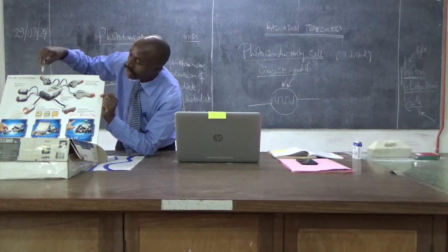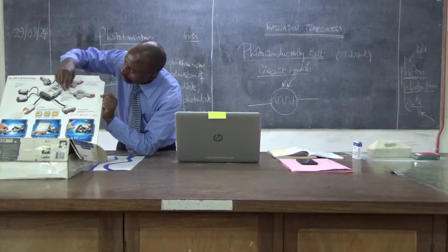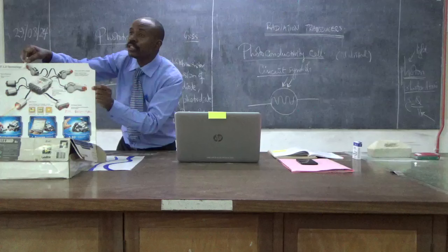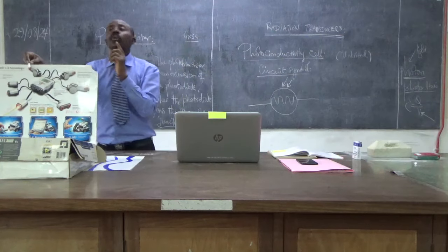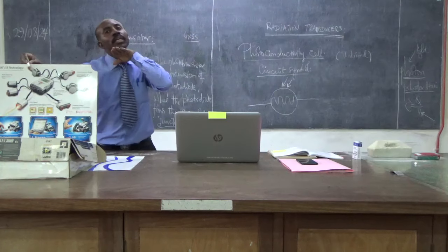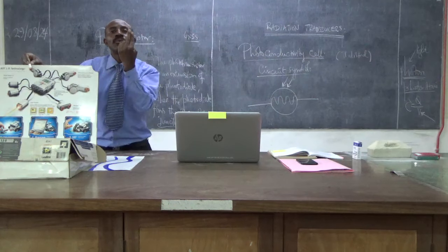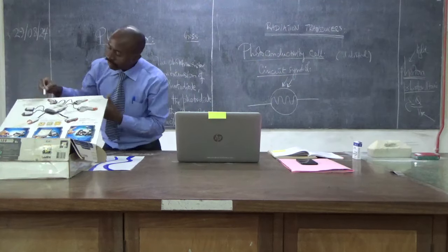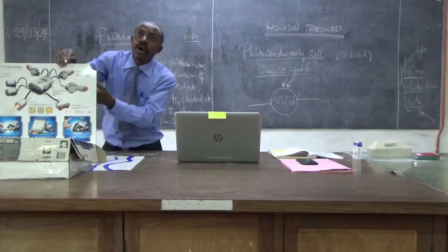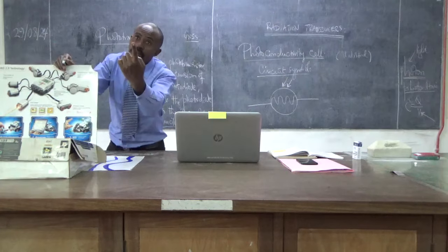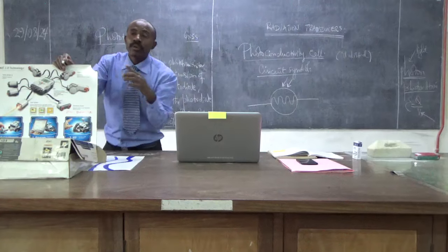This is a servo motor. These motors are for the legs. You can use it for the tires. The Explorer will use it for the neck, and you make it like this, so where the tire would have been moving, the neck is the one which is moving. Then you have the ultrasonic sensor. One sends the signal, the other one receives it. So when the signal goes and has come back, then you can tell it what to do.